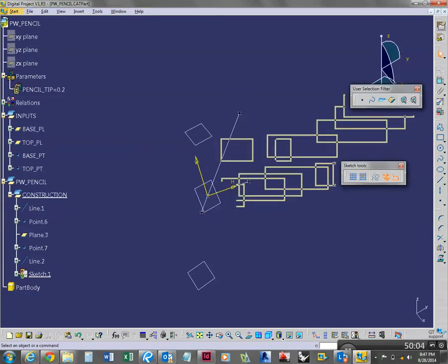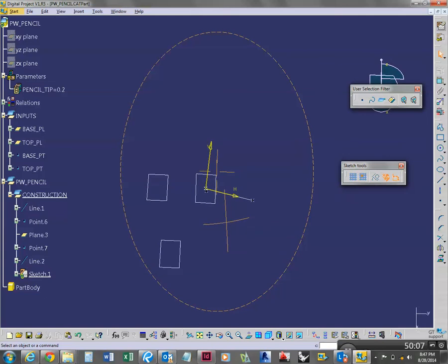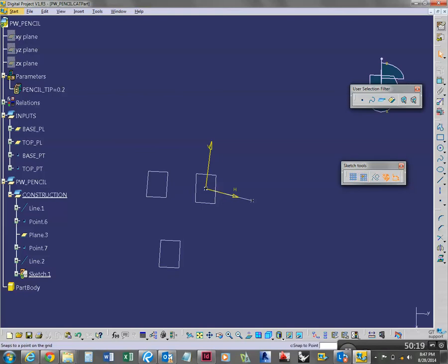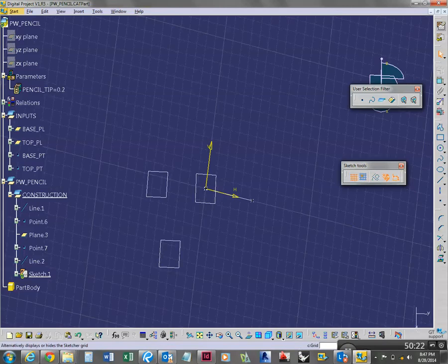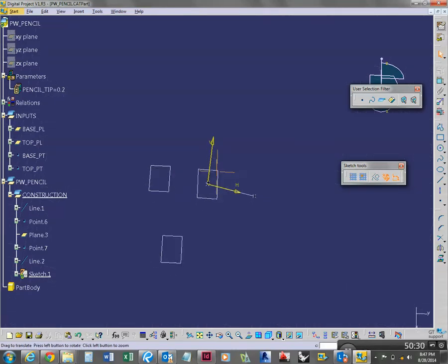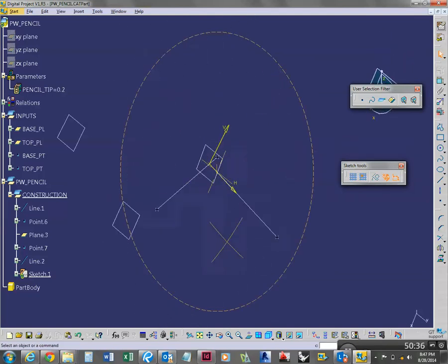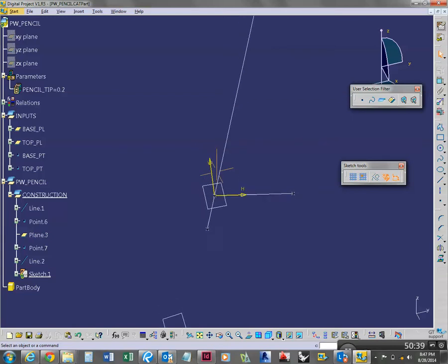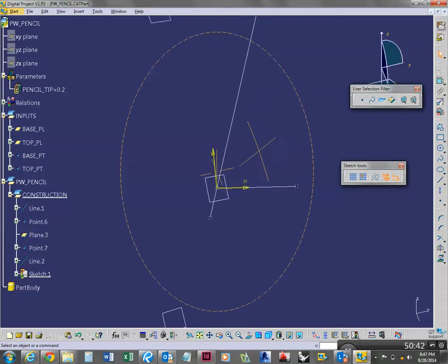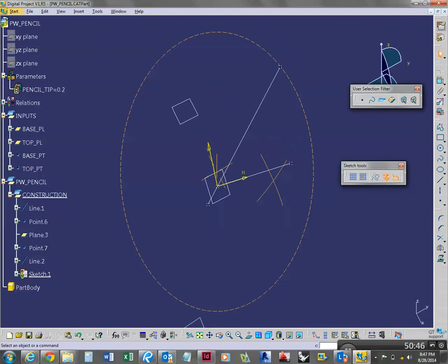and your screen probably resumed like that. Am I right? Did your screen do some rezooming perpendicular to that plane? I've turned that off by default. You can turn it off later. Leave it for now. Do yours have this grid? You can turn that on or off right here. I prefer not to see it, so I turn it off. And also, if you want to rotate out of that perpendicular mode, you can just rotate out. Hold down middle, hold down right, and you can rotate out of that.